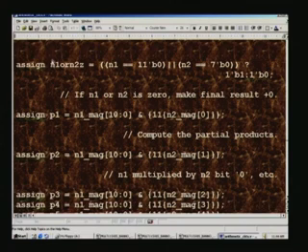And this particular statement evaluates whether it is a 0 or not. If the result is 0, this will be 1. That is what this statement means. See, if n1 is 0 or if n2 is 0, then 1 is put into this signal here, and this is a wire there. And similarly, we evaluate P1.